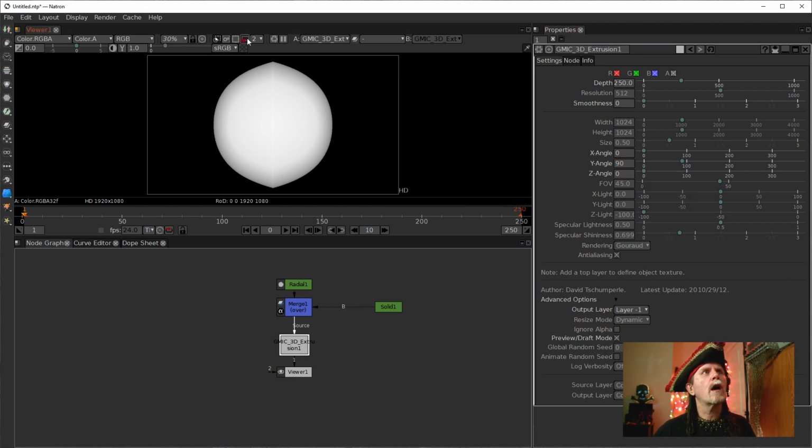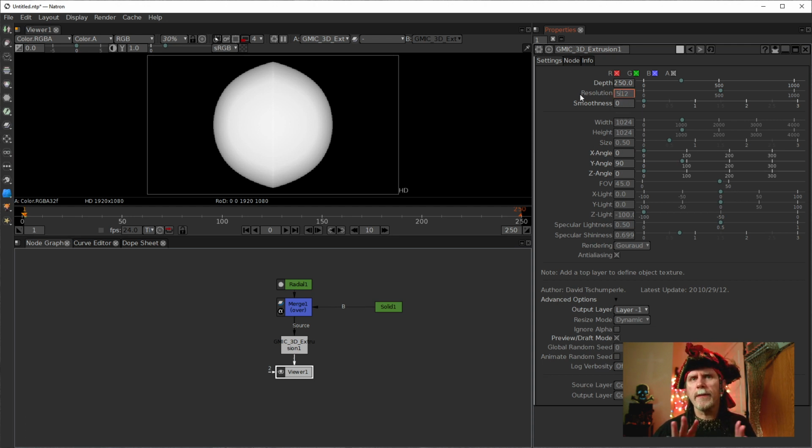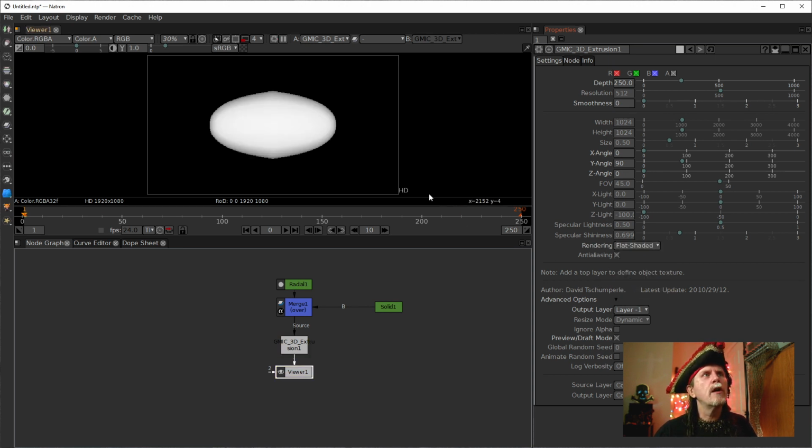First of all, let's lower our render resolution a little bit so that this doesn't take forever to do. And let's also lower the resolution of some other things here. So let's talk about some things we haven't talked about in the past, which is, first of all, what is this little resolution thing up here that says 512? Well, this 512 is actually how many... it's not really exactly how many polygons are in this. It's an approximation of how many polygons. If we switch this from Gouraud to flat shaded, we can...